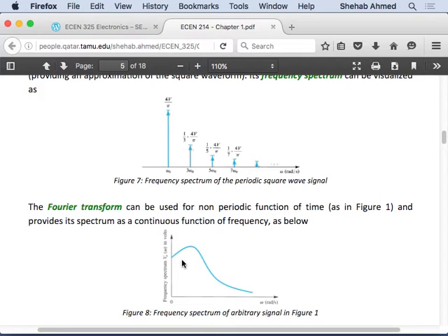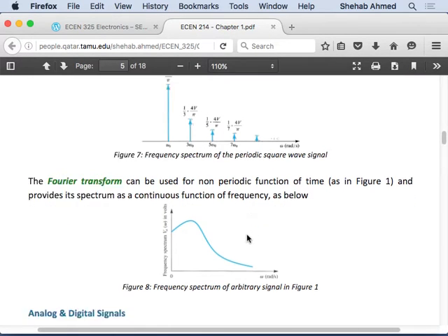Fourier transform gives you a waveform of frequencies. So at any point, you have a frequency component. Here, with the Fourier series, it's discrete. I have components at omega naught, 3 omega naught, 5 omega naught, 7 omega naught. I have nothing at 1.5 or at 2.5, right? Because the signal was periodic. If the signal is non-periodic, you analyze it using Fourier transform, and the Fourier transform output is a continuous set of frequency components. So at omega naught times 1.1, times 1.2, times 1, you will have a continuous waveform of frequencies. Just a subtle difference between them.